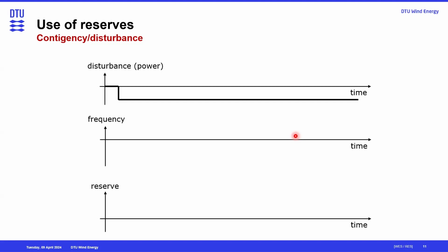So we have designed the reserves accordingly, so that we should be able to handle 3000 megawatt at any point of time. National Grid in the UK goes even beyond and goes to N-2 contingency, the reason being that it's an isolated islanded system and they need a bit higher security.